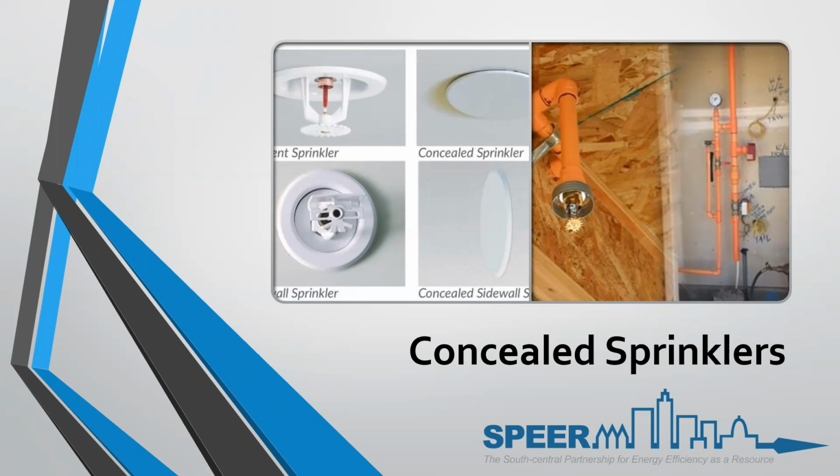So I've always tried to put my foot down and say this needs to be air sealed. It is required in code to be air sealed, but then it backs up and says, but it must be approved by the manufacturer. And if you look at any of them, none of them have an approved method of air sealing those yet. I think now that ACH is leveled out in code and it's no longer getting tighter and tighter and tighter, that may not ever really be an issue.